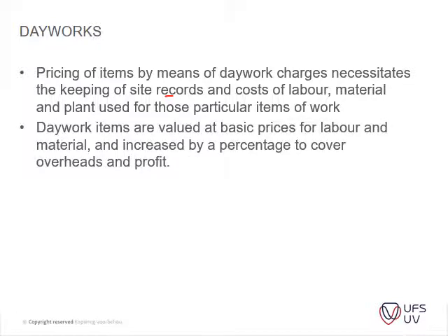Day work items are valued at basic prices for labor and material and increased by a percentage to cover the overheads and the profit. Yeah, so usually those rates are given that we spoke about here, and then the contractor usually has a separate item where he adds his profit and overheads to it, usually a percentage on that.